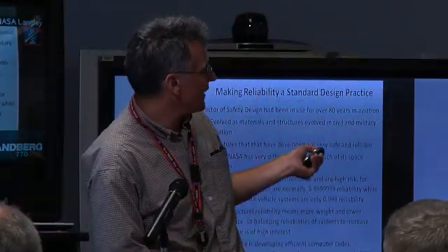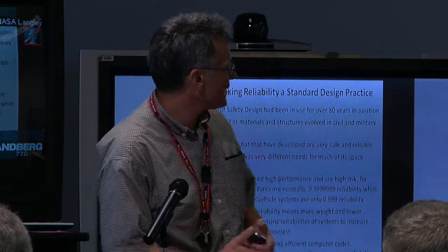So what we're trying to do within NASA is, even though we've had factor of safety design in aviation for 80 years, really, it's been around for a long time, and it's evolved as we've learned more about materials and structures. In fact, the factor of safety that's commonly used now is 1.5. 1.5 times your extreme load is your minimum strength allowable. Although NASA uses a little bit less than that, we use 1.4 instead of 1.5, so we're taking a little more risk, but not a lot.